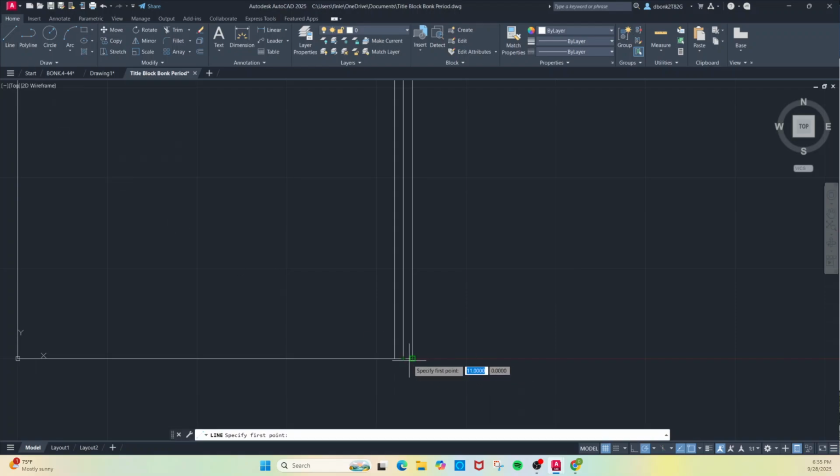All right, and just to show you the other way you can track and set up lines is by going to a point, like we're going to split this right side column into 3 equal parts, and I have to go up 2 3/4 inches and separate a line here. If you go over a point on a line and you start dragging upward or downward or whatever direction you need to get this dotted line here, you can type in the measurement that you're going to start the next line at,